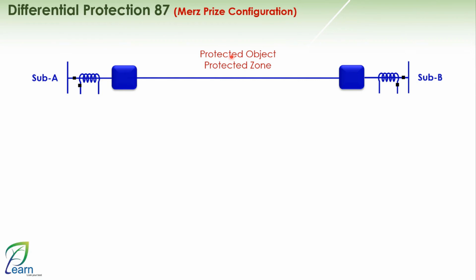On the transformers, or on what we are actually going to talk about, or what is the basis of our series. Differential protection differentiates between two things. What does it mean to differentiate between two things? It means you see the set of currents entering your system, and the set of currents exiting from your system, and you start to differentiate between these currents.